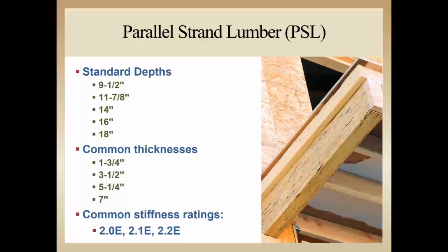PSL is manufactured in the same depths as I-joists and LVL and in thicknesses of 1 3/4 inch, 3.5, 5.25, and 7 inch. The members are also manufactured with similar structural characteristics as LVL of 2,900 psi in bending and 2.0E in bending stiffness or modulus of elasticity.